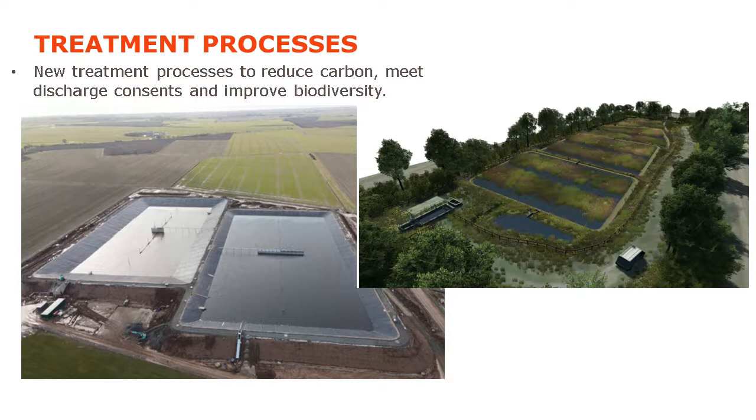The flow comes in on the bottom right-hand corner. It's pumped in, so there's an upgrade to the existing pumping station that feeds this works to get it to the new site. It then goes round in a loop. On top of those lagoons, there'll be some aerovac units, they're called, which are basically wind-powered aeration systems, paddles below the water surface that keep the bugs alive, keep everything moving, keep the wastewater flowing through the system. There'll also be aeration supplemented with diffusers, so there'll be some low energy blowers mounted at surface level between the two lagoons.